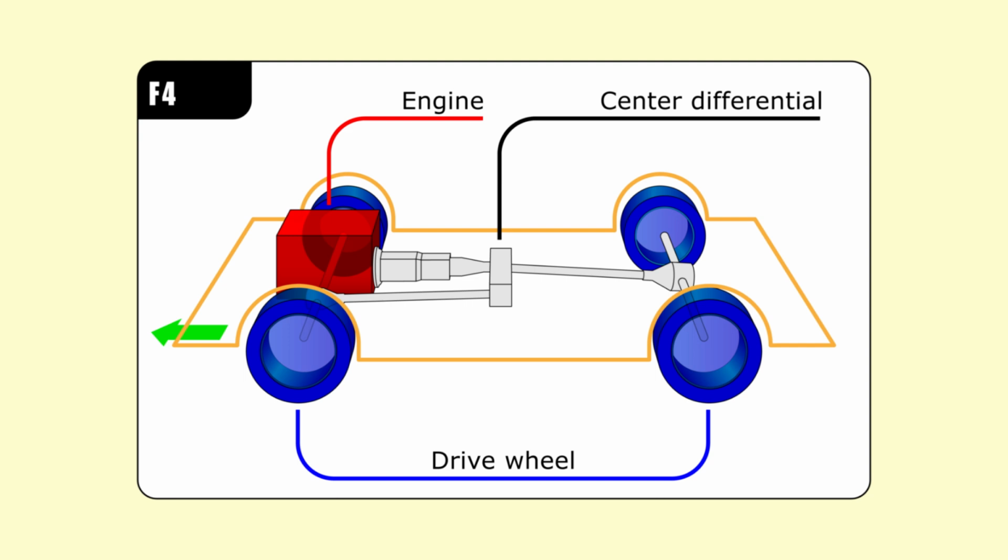And 2, all-wheel drive systems typically are heavier as they require more parts, and as power is sent through all 4 wheels, 2 differentials are now required instead of 1, as well as 2 half shafts. Applying some of the solutions already specified for FF, as they commonly share the same corner exit understeer woes due to front heavy similarities, can be a good idea.